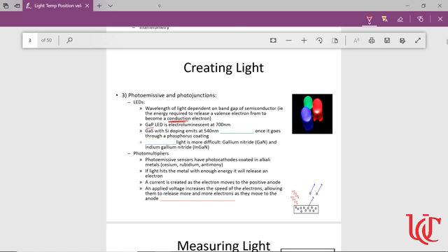So for example, gallium phosphide is an LED that will glow electroluminescent at about 700 nanometers. Anyone know what color that is? Red. If I have gallium, but now with sulfur and silicon doping, it's at 540 nanometers. Anyone know what color that is? Green. Oh, we're good with our colors. Okay. The green is actually helped a little bit, kind of in a fake version, by having a phosphor coating. We'll talk about that, but the light hits the coating and makes it release at a slightly different wavelength.